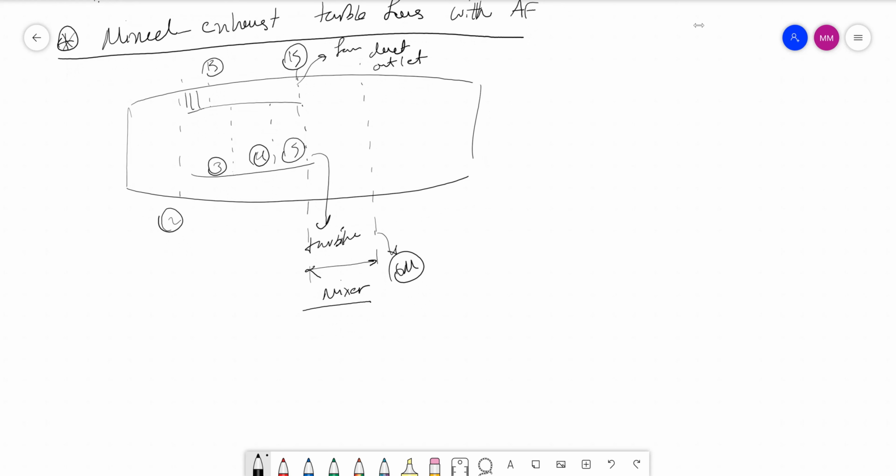And afterwards, we're gonna get the afterburner with the flame holders and the sprays, and you're gonna get the convergent-divergent nozzle. So 7, 8, and 9. So the main focus of today's lecture is going to be on analyzing this part. A combination of station 5 and 15 as the inlet and the station 6M as the outlet.